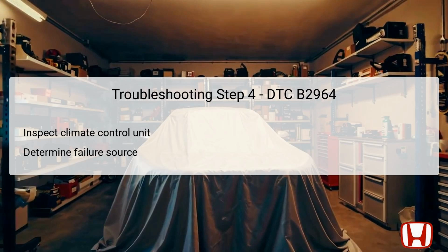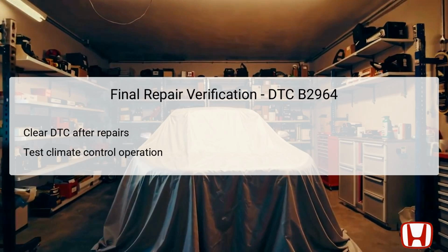This might include reviewing the connectors and inputs/outputs associated with the climate control unit to ensure they are secure and free from corrosion or debris. If this investigation reveals an abnormality, replacement of the climate control unit may be required to restore proper operation of the climate control system. After completing the necessary repairs associated with DTC B2964, it is important to verify that the